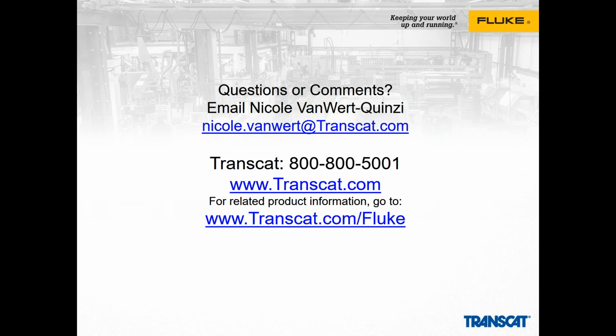Okay. If you imagine when you have a voltage dip, you're taking energy out of the system. And electronic equipment, as I've previously mentioned, takes the power in on the voltage side as a sine wave, or as a gulp of current. If you have a voltage dip and the dip happens to coincide with when you're taking the current in, then the energy won't be there to provide that current.